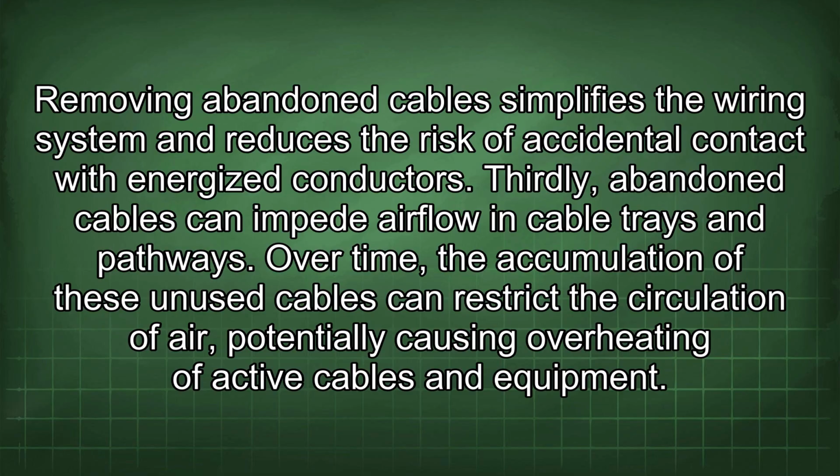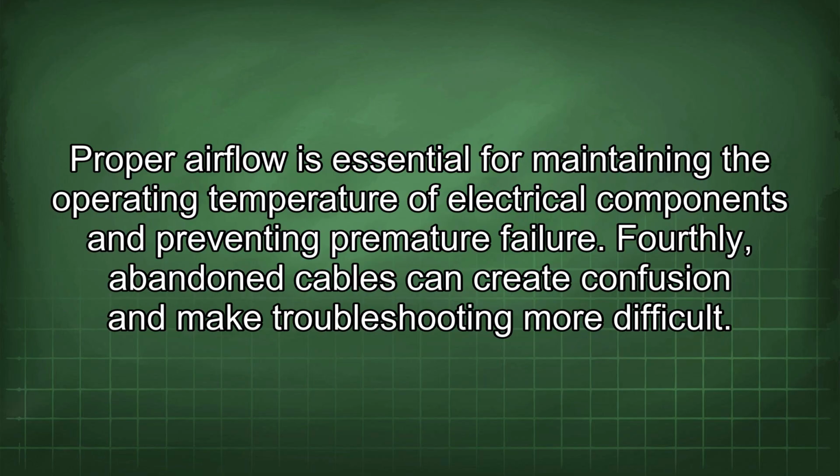Thirdly, abandoned cables can impede airflow in cable trays and pathways. Over time, the accumulation of these unused cables can restrict the circulation of air, potentially causing overheating of active cables and equipment. Proper airflow is essential for maintaining the operating temperature of electrical components and preventing premature failure.